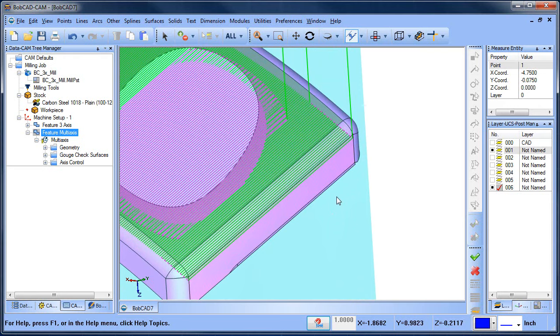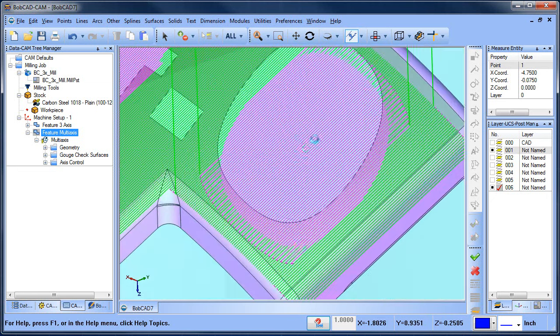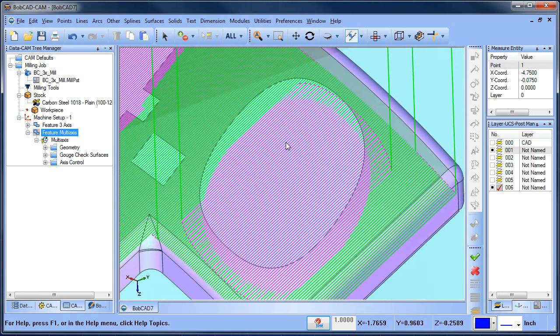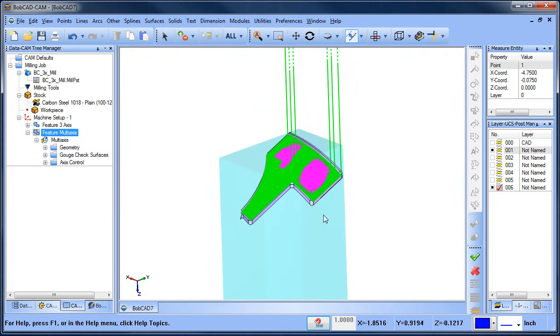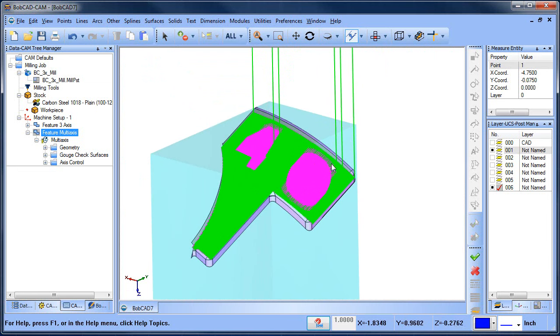Now this hasn't rolled over the edge of the part yet. Really all it's done is machined across this top surface here, but instead of having to plug in these surfaces, we've just told it to machine across it. That's a big advantage of the surface-based toolpaths: being able to control the gaps and also the links, and really allowing you to dial in your cutter path.